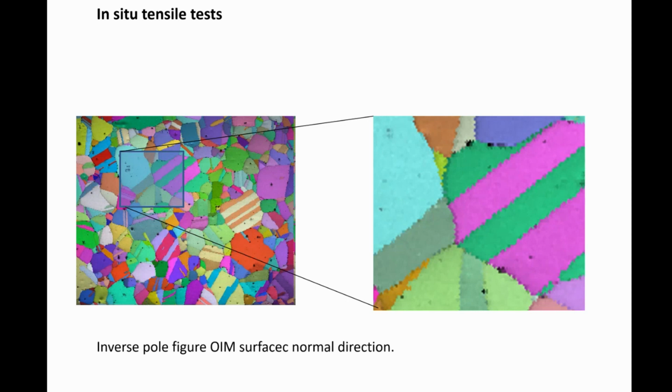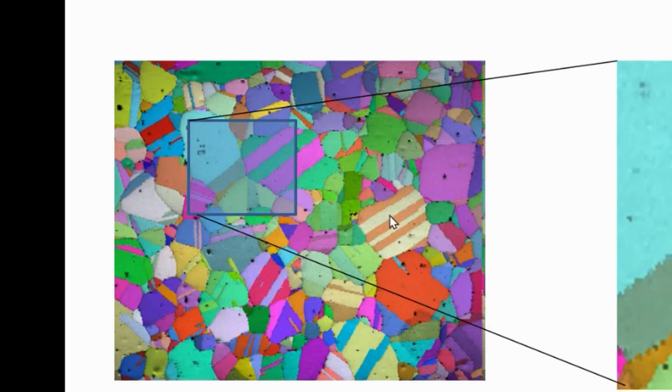The grain structure of the material is shown clearly. For example, just pick out some features here. Metallographically, everybody will recognize it as a twin structure in this material, which is a steel. These will have special grain boundaries. They're the most common special grain boundaries that exist in crystalline materials.